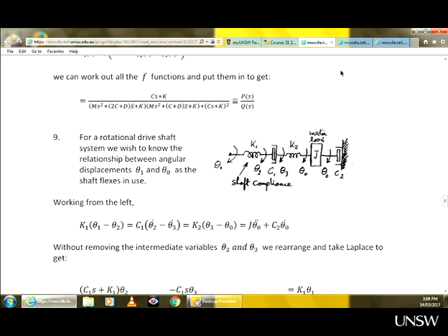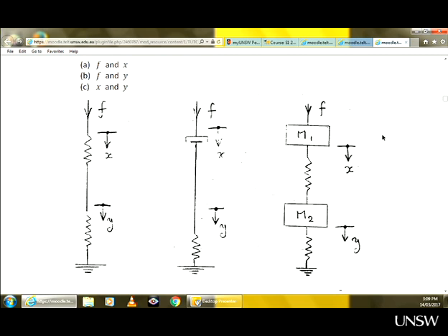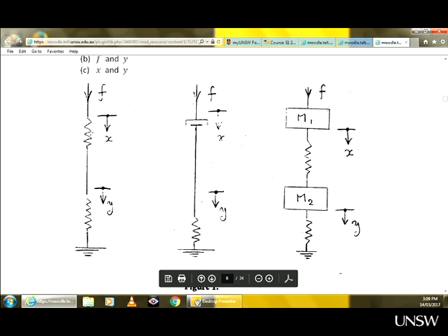This situation is similar to these systems here that you've already seen. Apart from here, you have linear displacements. You have force instead of a torque, and then you have linear displacements instead of angular displacements. So in this case, force is constant throughout this system. So the force in this spring equals the force in this spring. Over here, the force is constant again. So the force through this damper is the same as the force through this spring.